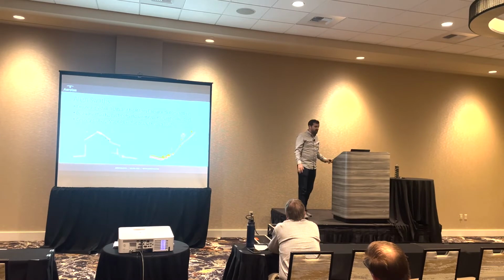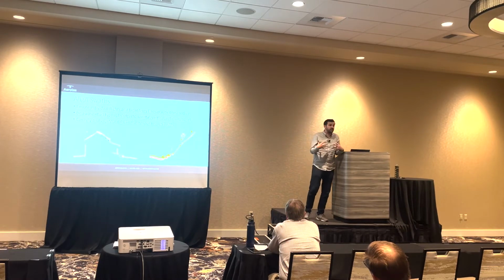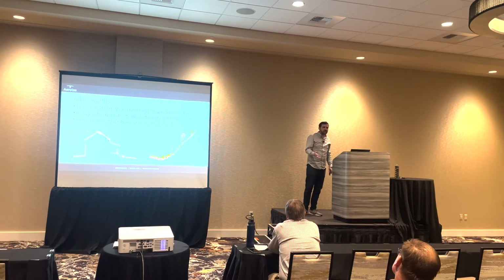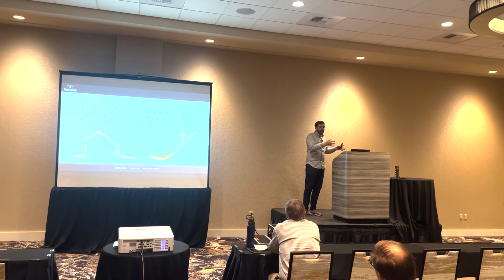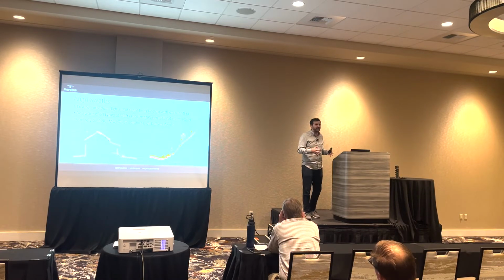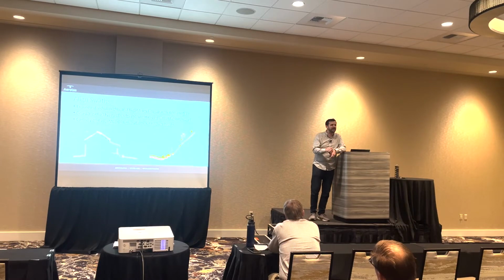So either works, and in fact, much of the data, we can't tell the difference what the base station is. We see a lot of the IMU data and what passes to the drone, and if it comes from a DJI base or a Trimble or Leica or anything, that works. Only reason we like the DJI base station is from a workflow simplicity. It's got like 3 buttons, you turn it on, and it just works. It's kind of crappy for surveying purposes actually, because that's really all it does. I would never use it as an actual survey rover or anything, but for streaming corrections to the drone, it's super user-friendly and idiot-proof.